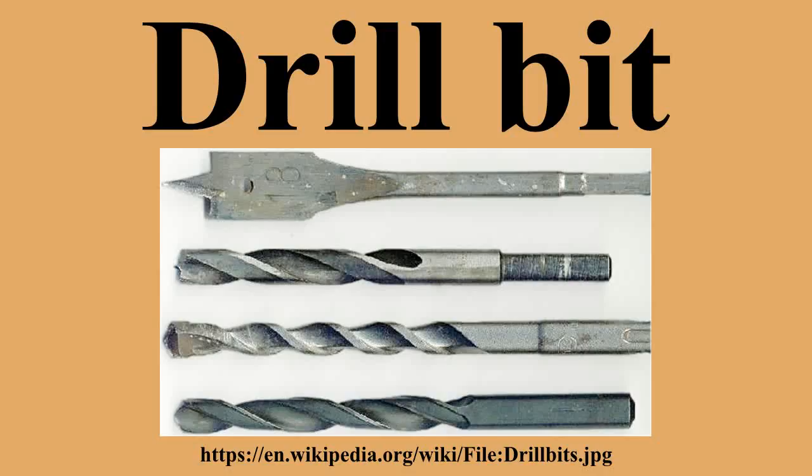Ejector drill bit, used almost exclusively for deep hole drilling of medium to large diameter holes. An ejector drill bit uses a specially designed carbide cutter at the point. The bit body is essentially a tube within a tube. Flushing water travels down between the two tubes. Chip removal is back through the center of the bit.